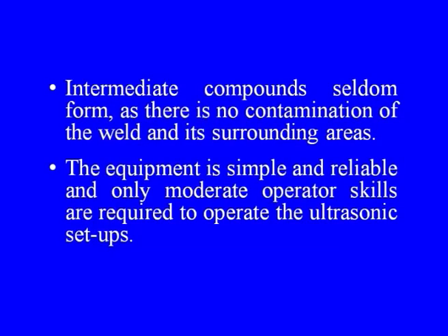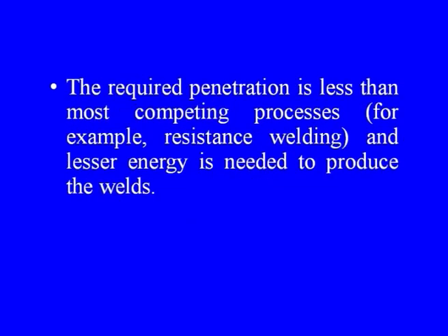Intermediate compounds seldom form, as there is no contamination of the weld and the surrounding areas. The equipment is simple and reliable, and only moderate operator skills are required to operate the electronically controlled ultrasonic setups. The required penetration is less than most competing processes, for example, resistance welding, and correspondingly lesser energy is needed to produce the welds.